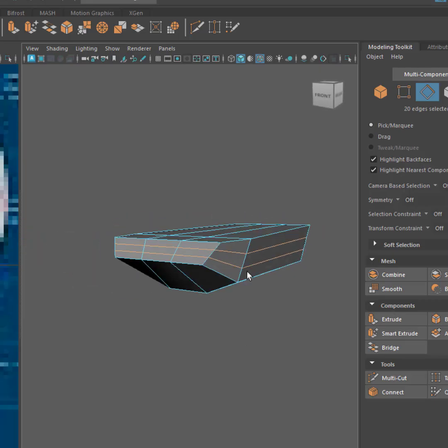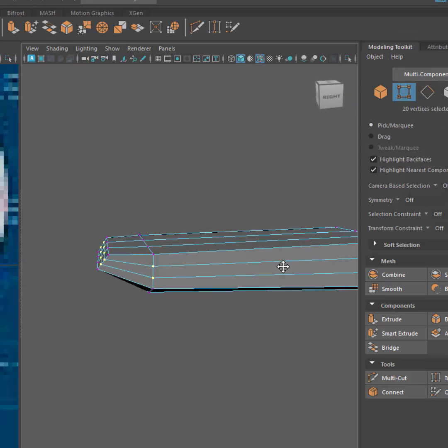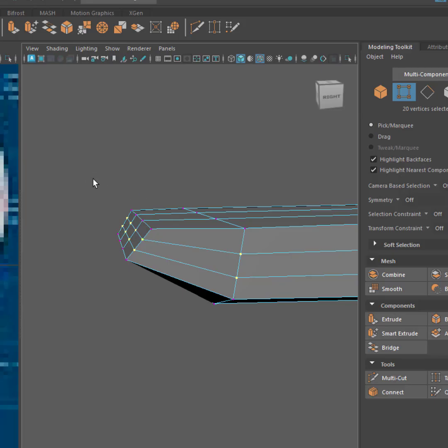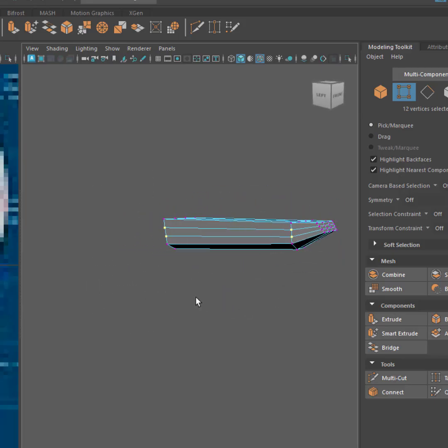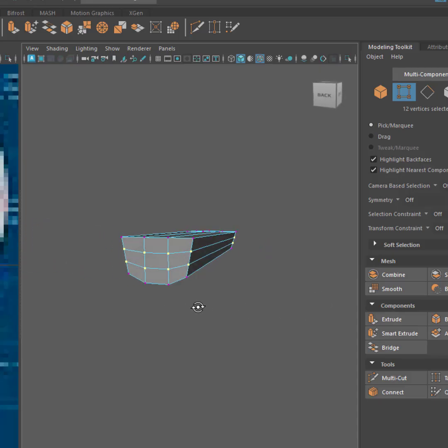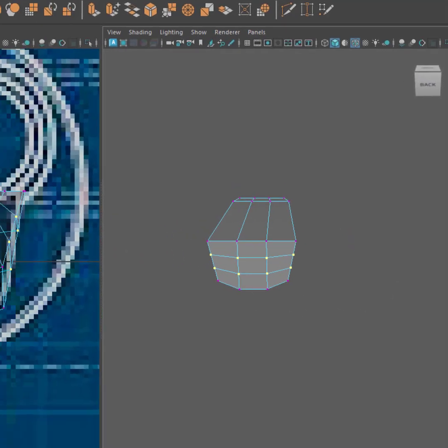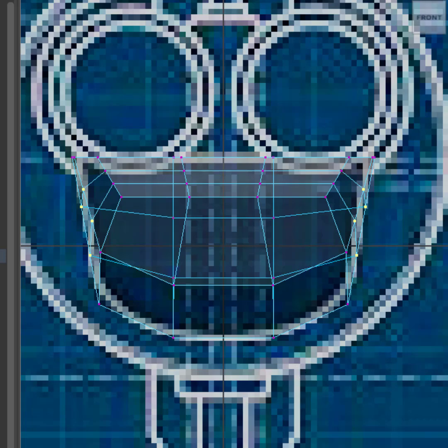Okay, then I will switch back, holding control. I'll select the vertex selection, and then deselect the front ones. Hold control and deselect the front vertices. I just need the side. I don't also need the front vertices here. There, I only need those.